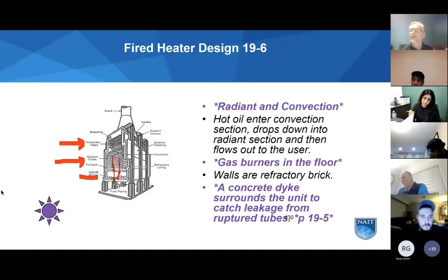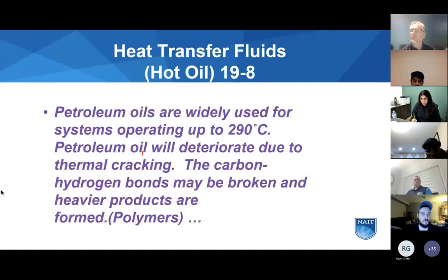When the tubes are around the flame in a boiler or furnace like this, it's called radiant tubes. Heat will go through into an upper breeching area, and tubes up in this section are getting heat from convection. They're taking more heat out of the gases as the gases pass through into the stack. So we call those convection tubes.